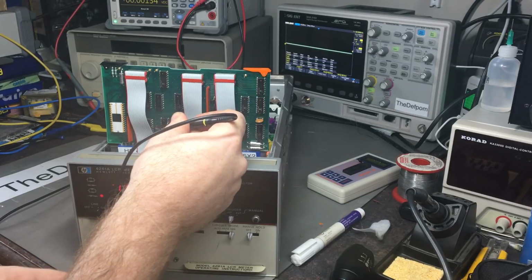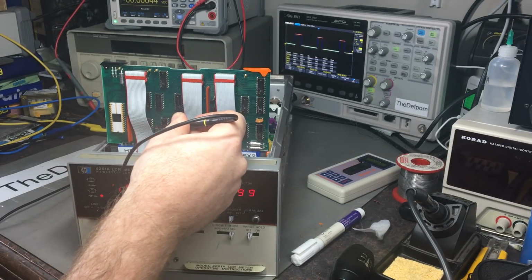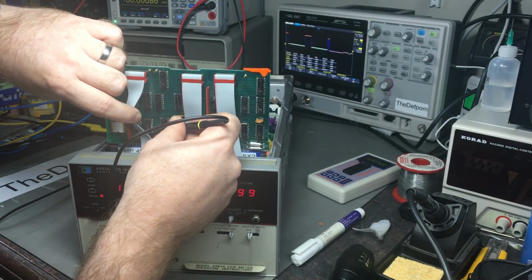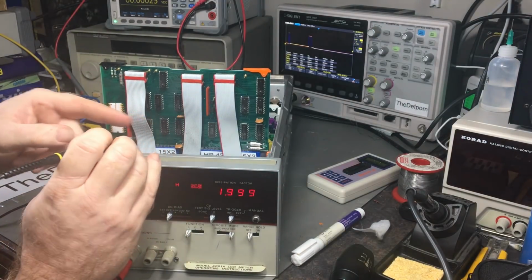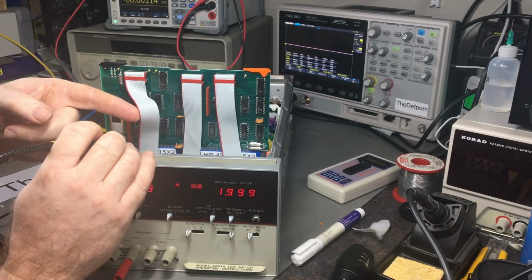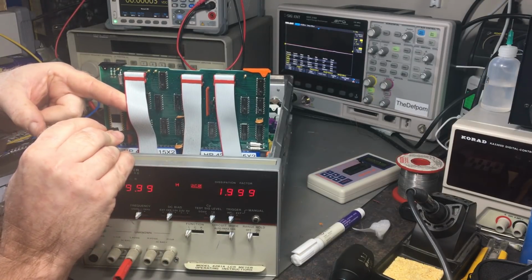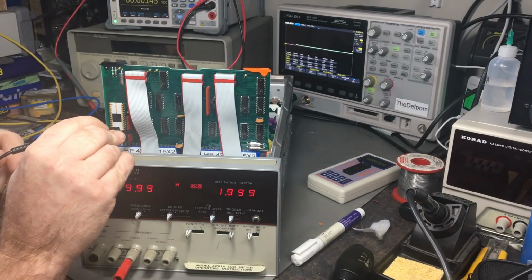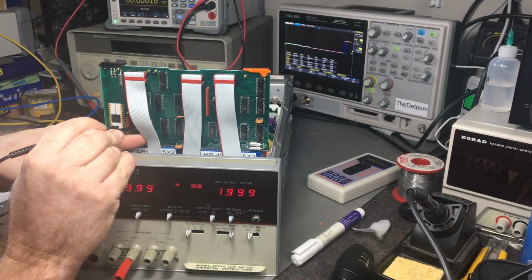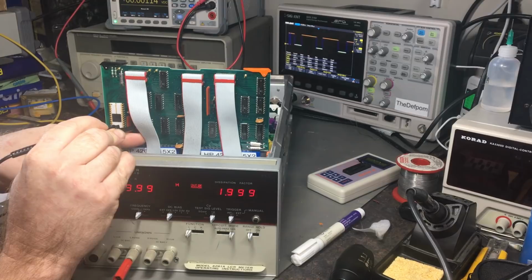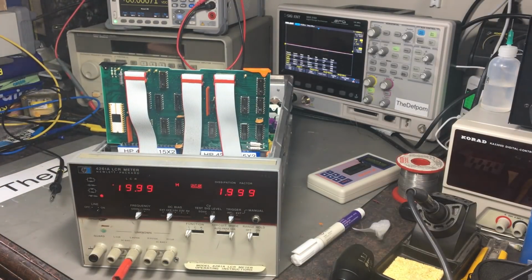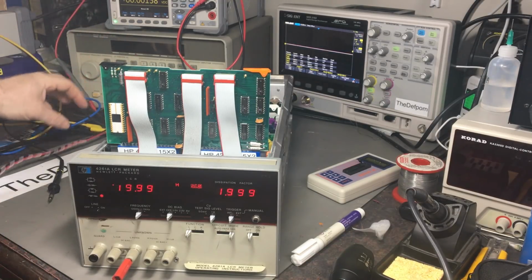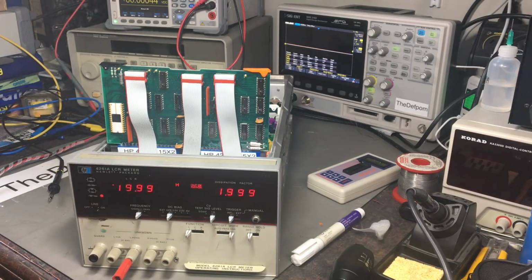Let's flick this over to serial or series. That should be pulsing. Yep. Pin 6 should be pulsing. It is. Sorry, pin 8 should be pulsing. Pin 6 should be low. It appears to be, and pin 4 should be pulsing. Yep, so those look fine. Can't fault those either. It's getting annoying, so I definitely got something wrong with it, but I'm not finding anything actually wrong in the test, am I? There's only a couple of things I've not been sure of.